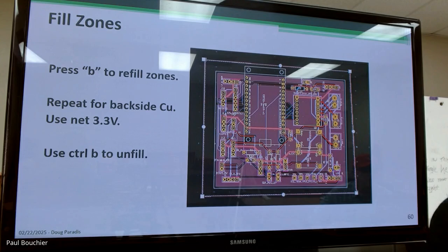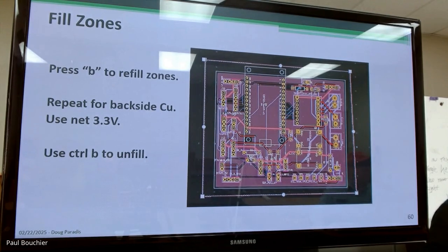Okay. Thank you. So this is an out of band question. Is there a way to easily flip the board around so you can see the backside view? Yeah, go to, okay, do you have them both enabled? Yes. Okay, go to the copper layers and click the show arrow. It looks like an eyeball. Okay, I see that. You can click on it for which layer you don't want to see. No, I just want to flip the board around. So you want to see it on the backside, yes. Like if I was placing backside components.